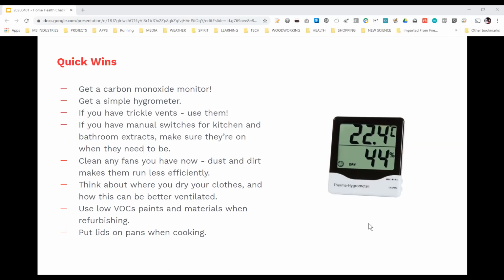The trick, though, is to not source that air from the living space. If it's possible to take it from a different space, either by putting a hole in the subfloor void, or in one case that I did, I actually pulled a pipe out of the bottom of the first floor flue and ran it between the floorboards to the outside. So this gave ventilation, but without drafts.